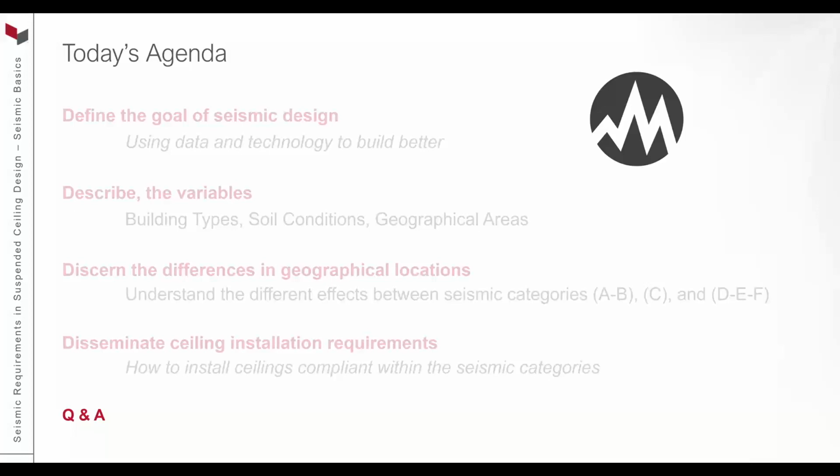So we would have to put rigid bracing in that so that we have a fixed and a floating side of the ceiling. And just for clarification, the 3/4 inch gap and the 3/8 inch gap that is required by the ASTM is for the movement of the wall, not so much the movement of the ceiling. They found that the walls bow and move during a seismic event, and they can compress. And if they compress against the ceiling, it could cause failure. So that's where the gaps at the perimeters or on two sides of the perimeters come from.